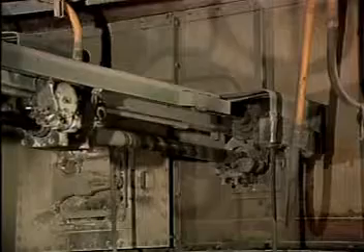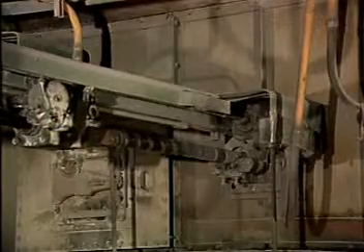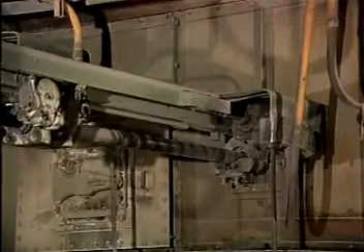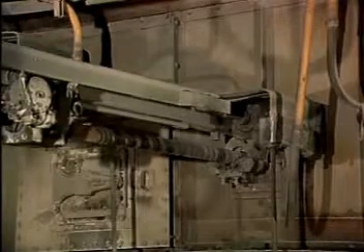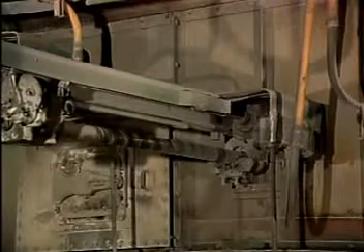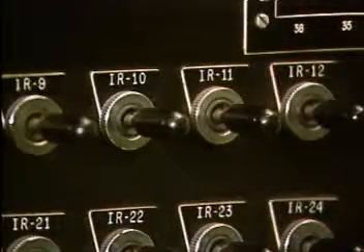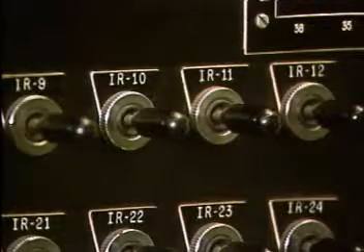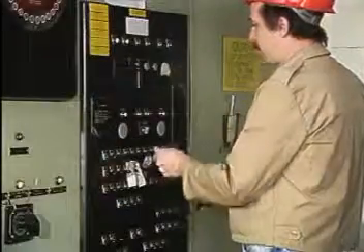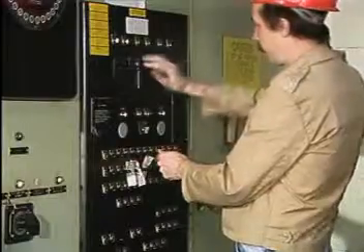In most cases, both types of soot blowers are retractable, so that the lance tube can be inserted into the boiler while soot blowing is in progress, and then removed when it's not needed to prevent heat damage. The soot blowers are typically programmed to operate in a predetermined order to ensure proper cleaning of the boiler tubes. However, there may be occasions when you'll need to manually bypass a certain soot blower or manually retract a soot blower that will not respond to automatic control.